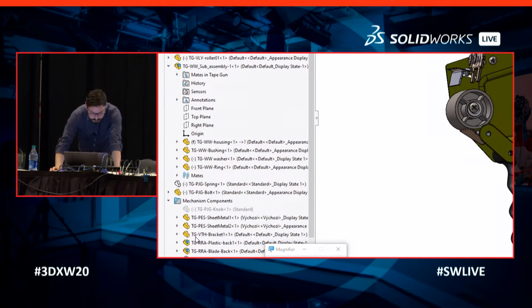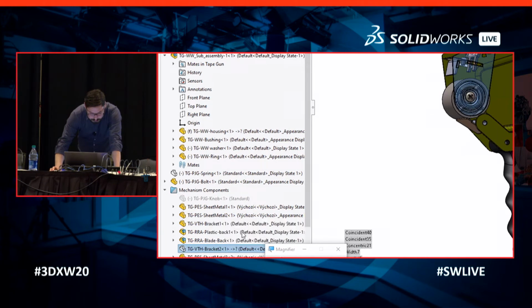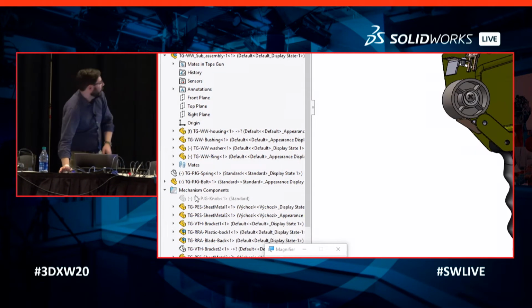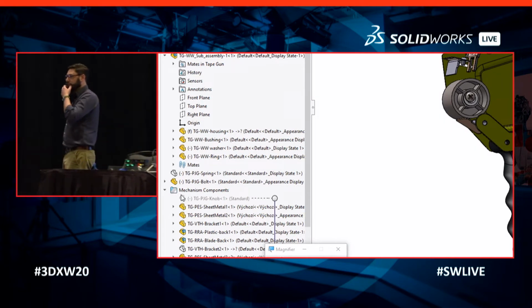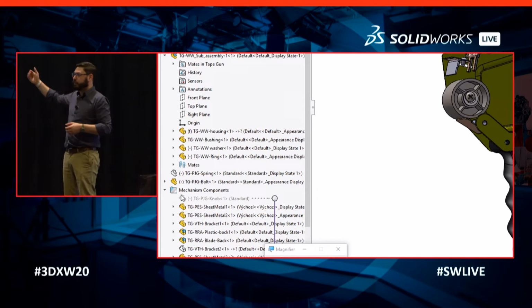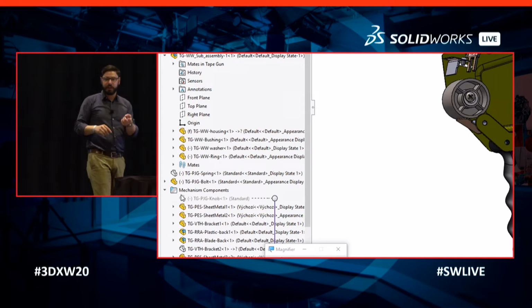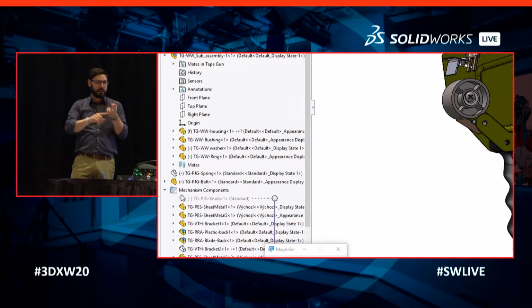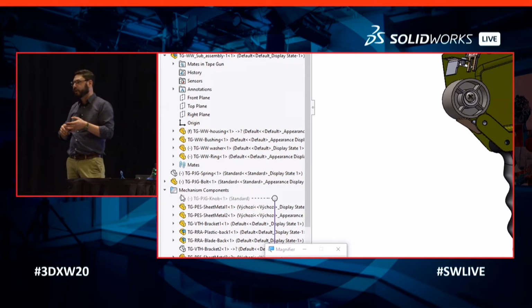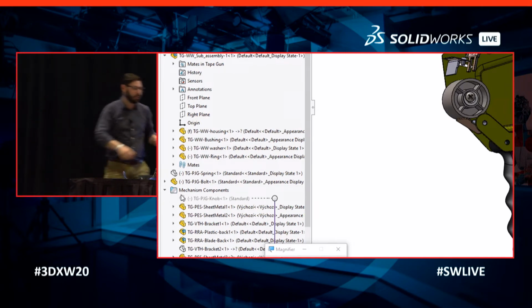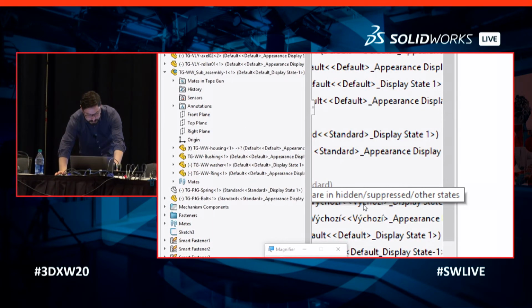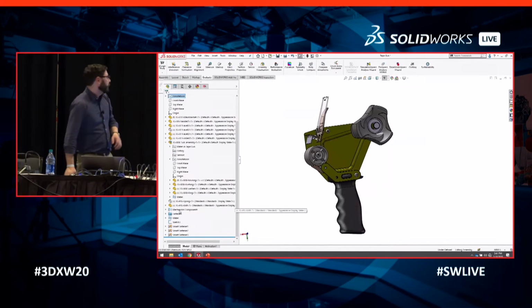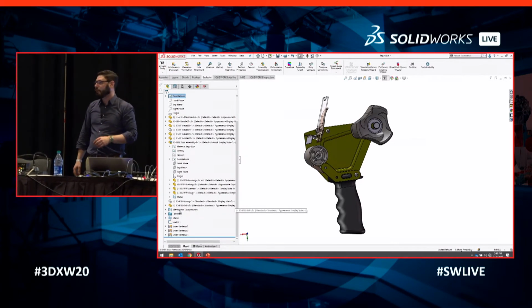And then if I hide or show components in here as well, that will actually have a third color to show that some are hidden, okay? So there's like a blank one in there, so that's a third color. So inside that folder are not only resolved components, but suppressed components and hidden components as well. So, at a quick visual glance from the top level, I can see that there's a lot of stuff going on inside this folder. There's components that are both suppressed and hidden, right?